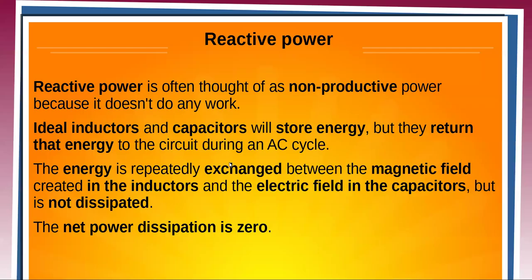Okay, so reactive power is non-productive power or wattless power because the inductors and capacitors just store the energy and they return it back, except for a little bit of loss because they're not perfect. But in theory, they don't dissipate any power, so the net power dissipation is zero.